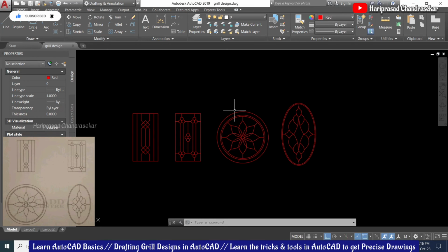So have you seen that? Yes. So everything here we need to start without dimension. Later with dimension also we should practice. See this one, the door and all, you can use multiple copy, offset, and then mirror options. So only half thing you need to do, so that then only you can maintain the mirror. Then the door, the second door, they're using only the spline and then the arc or the circle. You can trim also. Like that, it's up to you. Yeah, we will do that.